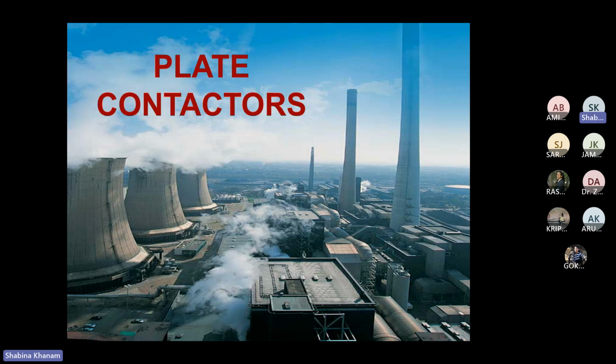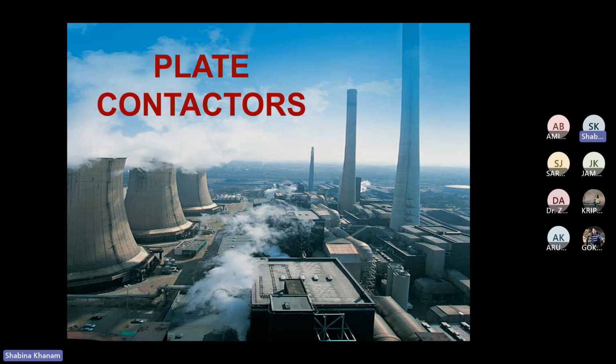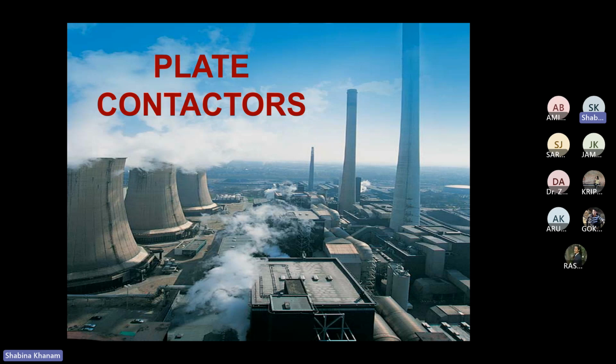Plate efficiency is how the mass transfer is occurring on a single plate, it counts that. Along with that, we have discussed the column efficiency also. The column efficiency basically counts the overall column efficiency. So if you have a number of ideal trays, you can find out the real trays. That is the overall column efficiency we have discussed considering O'Connell's method.